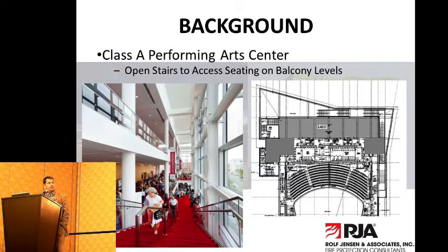This is all open space, kind of a unique design, open stairs. And I guess the hitch, as to why it was a little bit different than a typical box or cube atrium, is that the atrium space actually wraps around the seating a bit. So it's not shown here in gray, but these side stairs are all open to the atrium space. And so we got a lot of these narrow pockets, corridors, and spaces that certainly make smoke control a bit difficult if we're dealing with how we're going to make sure we get effective smoke control, allowing people to circulate or use the space in their egress paths.